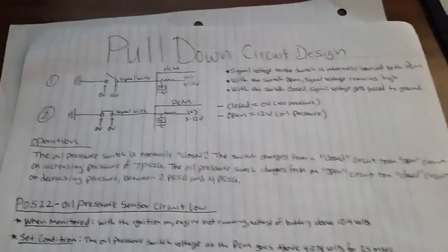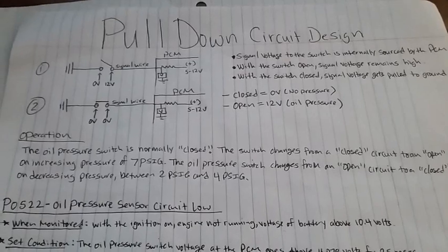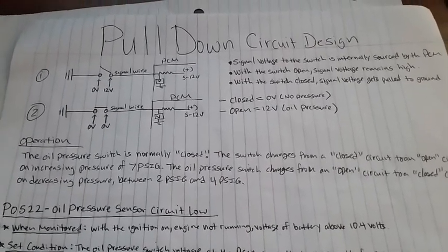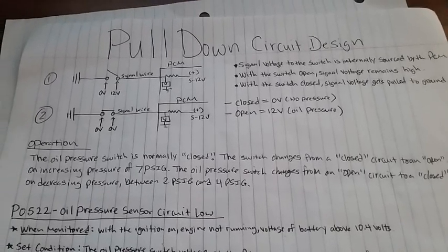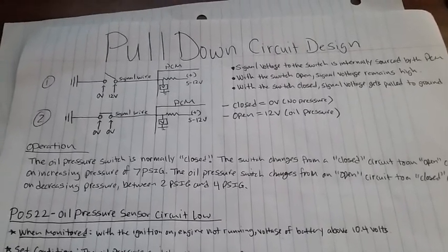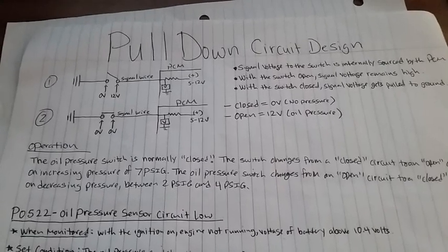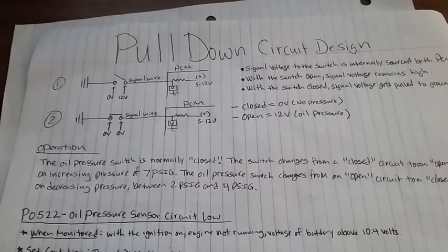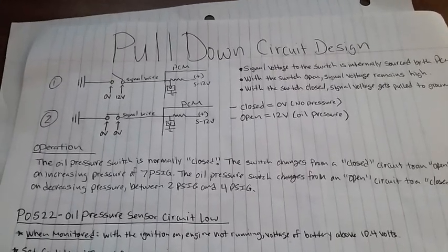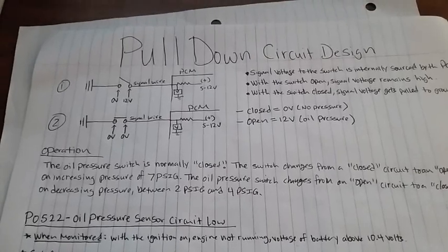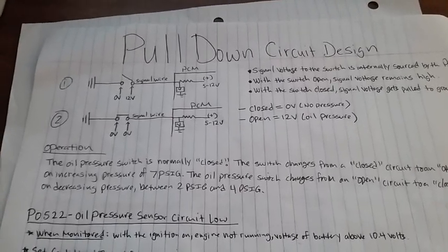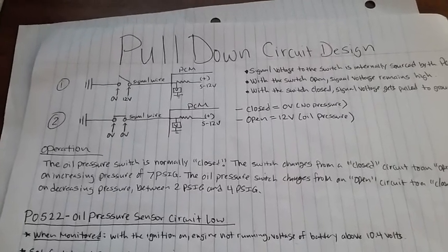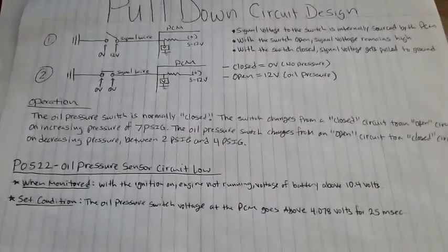And on these Chrysler PT Cruisers, normally after a shutdown, after 90 seconds, the pressure inside the oil pressure sensor should bleed off and go from an open circuit to a closed circuit, and the 12 volts should drop to approximately 0 volts again. That's a good indication that the circuit is working and the sensor is working. So let's go out there and do these checks.